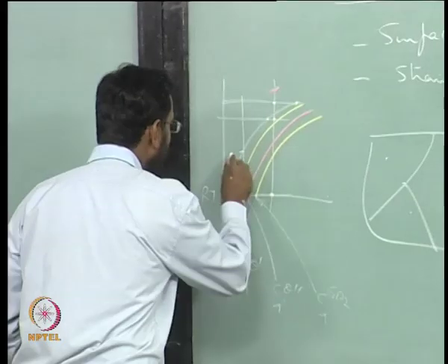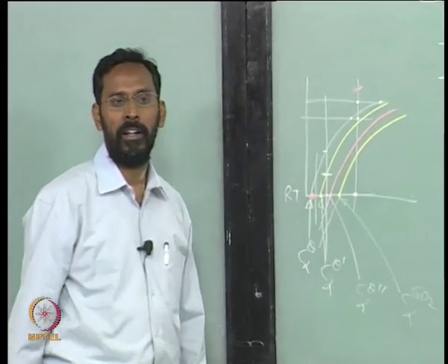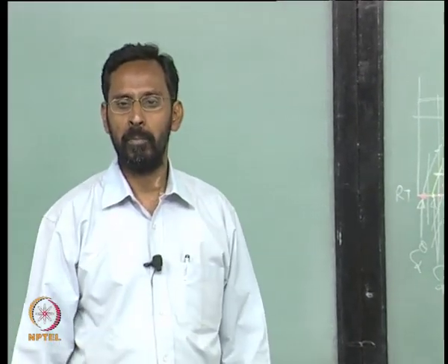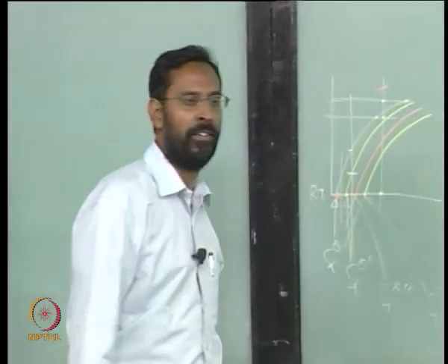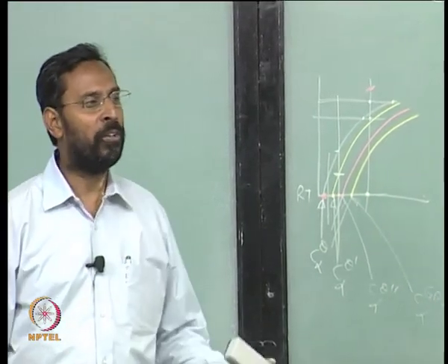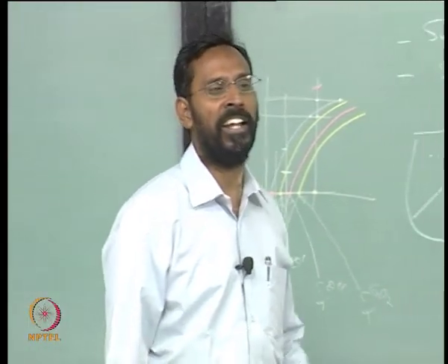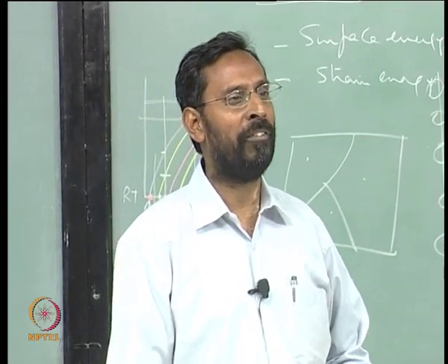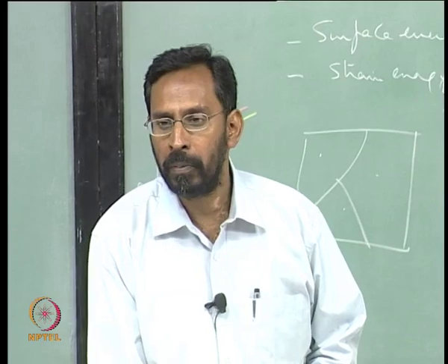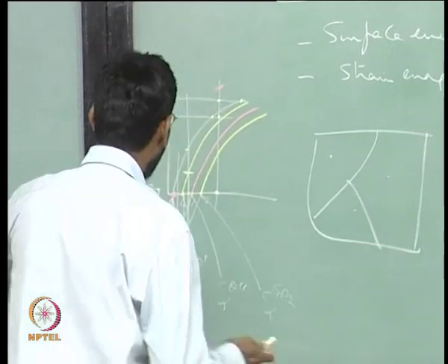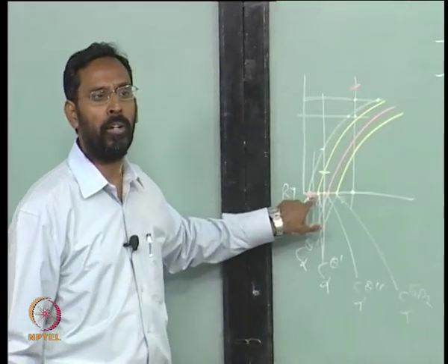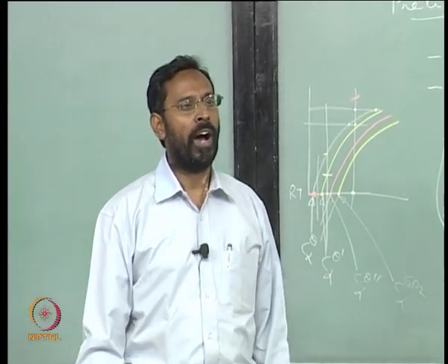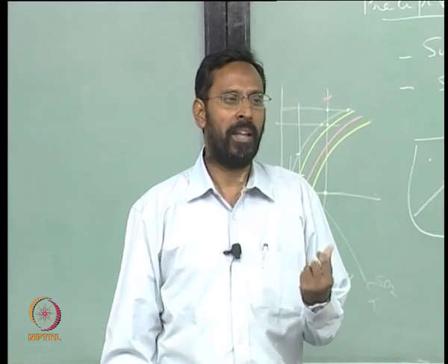If I choose an alloy of this particular composition, the only phase that can come out is theta if I bring that alloy to room temperature, and that is why we do not use such alloy compositions for age hardening. You will never think of age hardening a 1% copper alloy, because for such an alloy the only precipitate that can come out is theta, and you know that it is not going to give you higher strengthening, because it is incoherent.